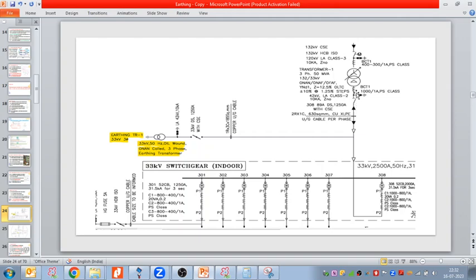For that, we just take the tapping from the conductor, and we can connect here this resistor and the disconnector. This equipment is just for the protection of this earthing grounding transformer. And here we take a two winding earthing or grounding transformer, right? On this side, could you follow my cursor?